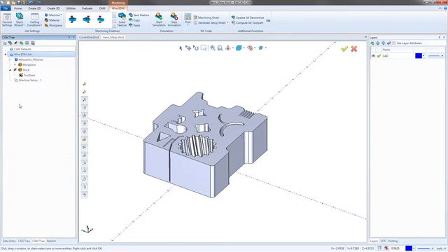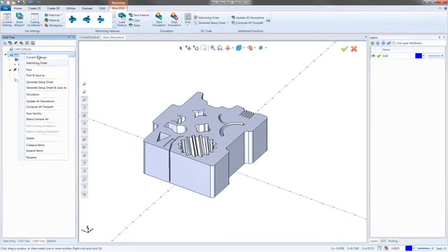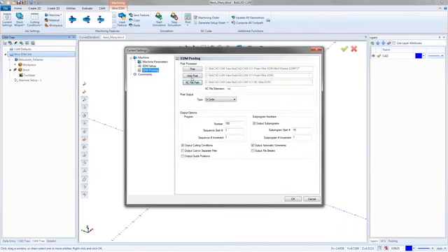Now, if you can figure it out, you can actually go into your CAM defaults or into your Wire EDM current settings. And on the EDM posting tab, there is an option for output cutting conditions right here. And so the cutting conditions will output.